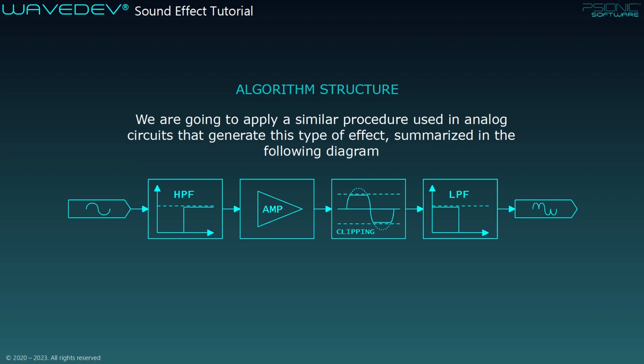The first stage consists of an adaptation filter, which has some special characteristics that we will discuss later. This block can also be called the pre-saturation stage. In my opinion, this is the most important stage of our effect, since we define here the DNA of the distortion. If the signal is not correctly adapted before saturating, all subsequent stages will not be able to fix a bad sound.